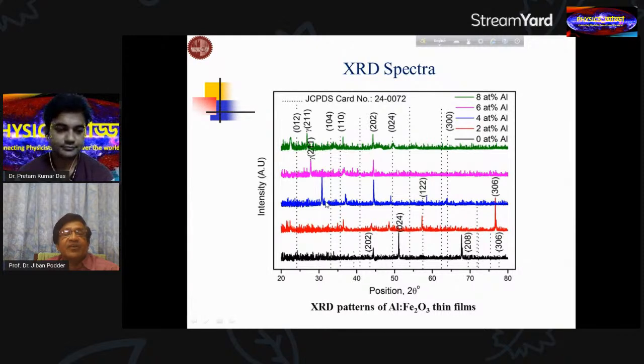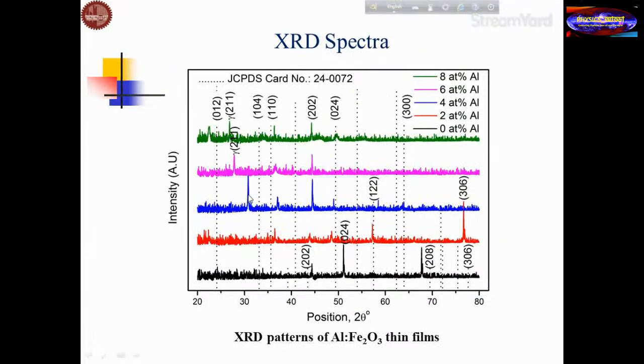These are the X-ray patterns. Already I mentioned the position, the intensity, and the width of each peak, for the direction or plane, whatever we say. This is the indexing, the Miller index, Miller plane. That gives you the position of the unit cell, its purity, and the intensity gives you the position of the atoms, and mainly the full width at half maximum gives you the crystallite size.